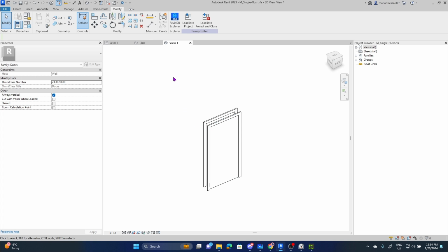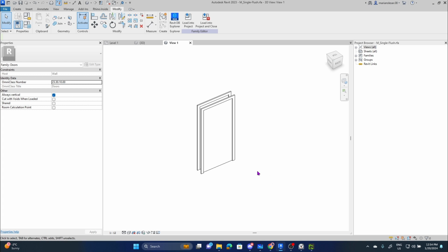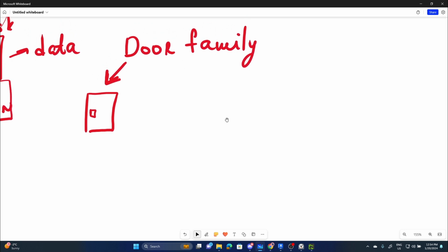The main idea is that if we solve problems in a paradigm similar to object-oriented, eventually that can be easier for us to understand how something works. For example, instead of creating each of these as just an extrusion, you can put this into a separate family and call this panel. This way, if we go back to our drawing board, now your family is not going to be just a bunch of geometry.